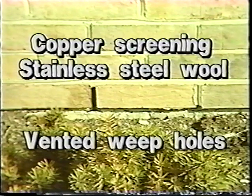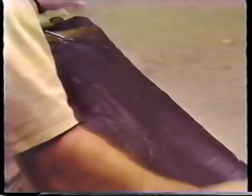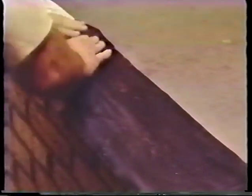Open weep holes could allow insects to build nests in the hole, clogging it up. You can prevent this by using copper screening, stainless steel wool, or vented weep holes in open head joints. Proper flashing and weep holes are necessary to get rid of water that has penetrated the brickwork. Its correct installation will avoid many of the potential water-related problems.